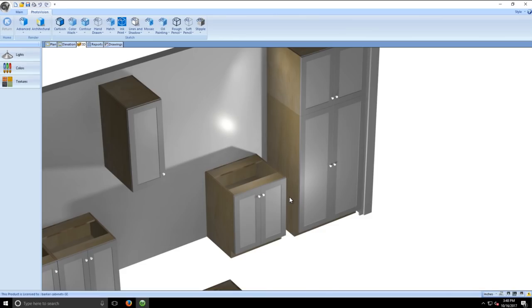And you don't have to worry about the cabinets not being able to stand up in the house. That could be an issue. If you hit the ceiling with a 96-inch tall cabinet, or 92-inch tall cabinet, how are you going to stand it up? Imagine the measurement from the front toe kick to the back top, if that makes sense. You won't be able to literally stand it up to install it. It's not a good deal. But when you have two pieces like this, you install the lower piece first, and then you just install the upper one afterwards. That's really easy. In fact, one person can do it.